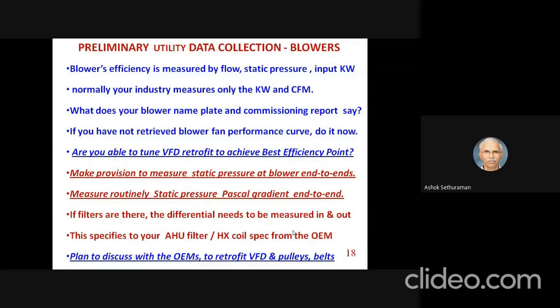If you are able to do a VFD retrofit, this will facilitate the pump or the blower to operate at the best efficiency point or a best efficiency band. So make provision in all your blowers. Tell the clients or the industry to make a provision with a drilling machine in the ducts, especially in the blowers, to monitor static pressure at the blower end and at the delivery end. Both, end-to-end monitoring, is also important.